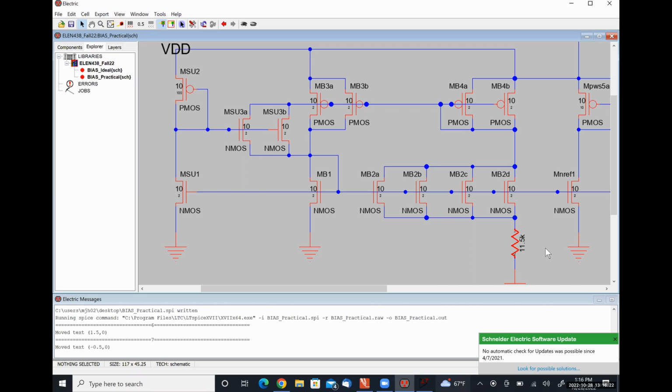Yeah, and so I just did a transient for 5 milliseconds or something like that. It really doesn't matter. You could technically do a DC operating point as well. I'm probably butchering the .tran syntax, and then 5m. Just 5m. Yeah, no space. V0 DC 5. Yes.